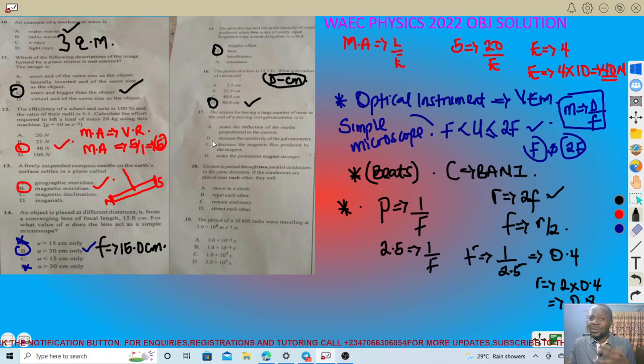So I'm not going into details of teaching concepts. I only want to focus more on your answers and why we are picking the right answer. So this is the answer. The increase in sensitivity is that the torque is proportional to this. And of course, sensitivity of a galvanometer is always the current over the scale of angle deflection. So always keep that in mind. This is what we call current sensitivity. They are available on my channel. You can always learn.